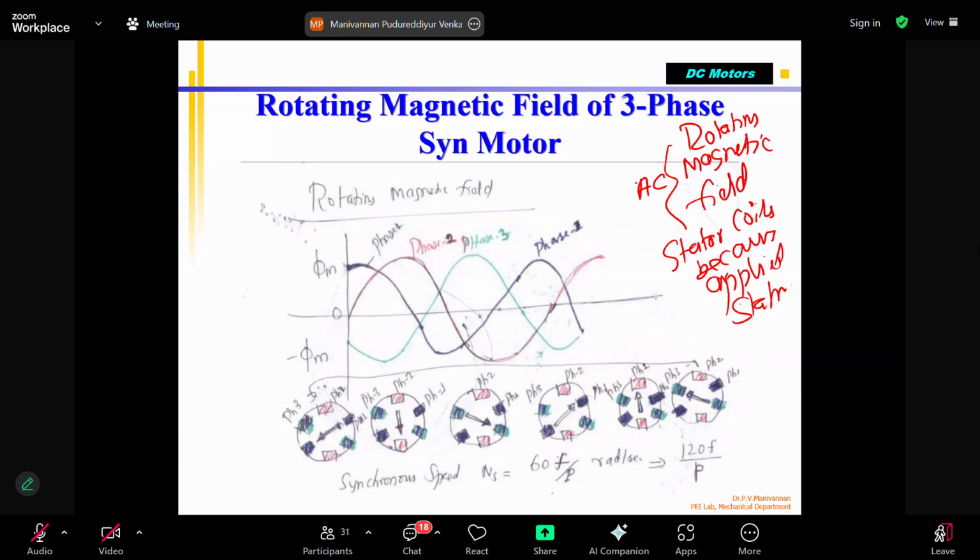So what it does is, initially the rotor was like this. I told you, before you apply the voltage, the rotor can be in any position. For example, it was like this. You have not applied any voltage to the stator. The rotor has voltage applied. This is north pole, south pole. Once you apply the AC voltage at T equals 0, the voltage starts increasing. Everything is varying. But at the time instant when the blue has the maximum, for understanding purposes, the rotor is pulled and aligns with this at this time instant.